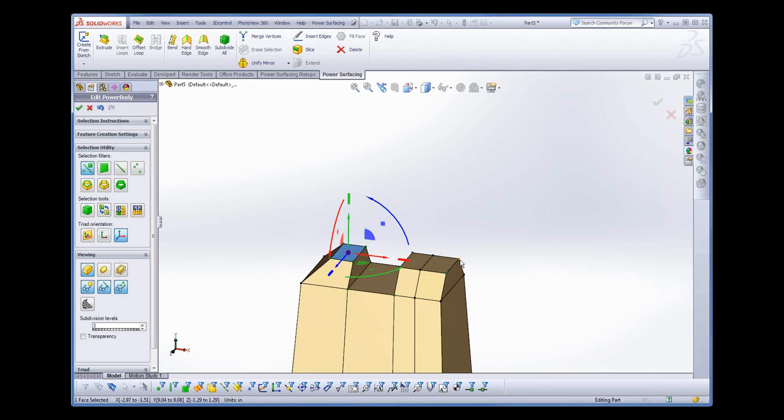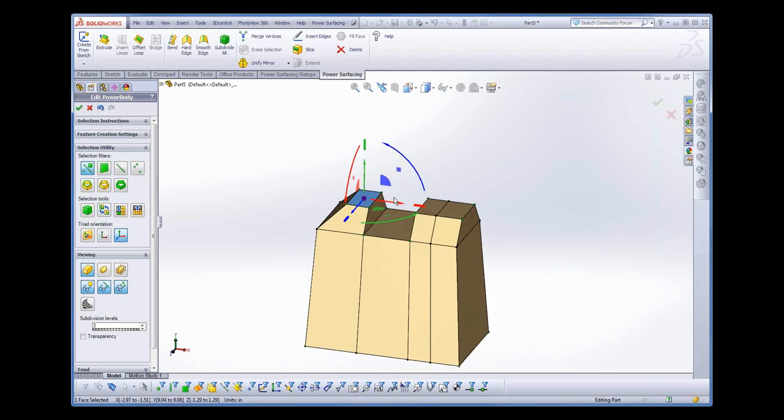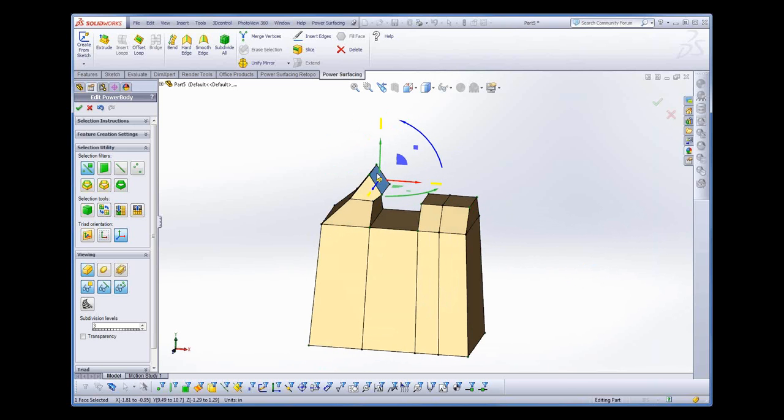And holding my A key, I'm going to extrude this. And I'm going to rotate it. Now the problem is, as soon as I rotate it, you can see that the dimensions have sort of changed because of the orientation. They haven't really changed. They just look different. And one of the things we can do is switch between world, screen, and the object itself. So I've changed to the object coordinates, and now I can scale this guy back down and get him right where I want him. I'll go ahead and hold my A key again and extrude, give it a little rotation.